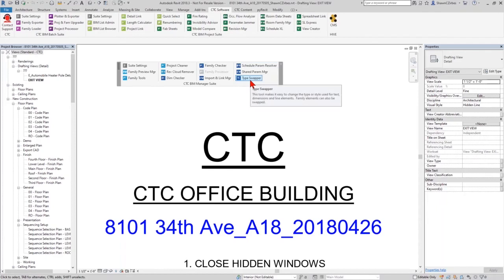The family cleanup side, well, Shared Parameter Manager is absolutely your starting point for this, being able to bring your shared parameter file into a good standard. And I'm going to show you this tool because this one's super powerful on the family cleanup side. Family Processor is fantastic to go through and actually clean up your content. And you may want to run Family Checker first to understand just how out of compliance certain portions of your library are, and then run Family Processor. So those 2 tools can play together well.